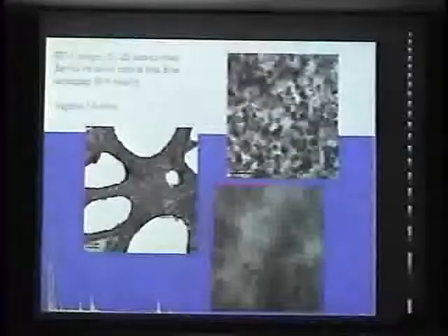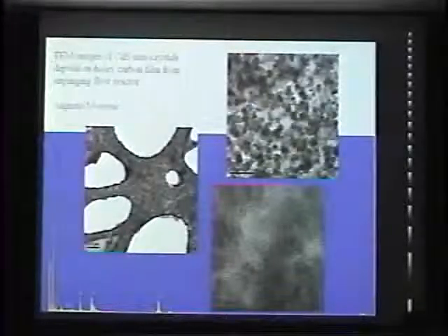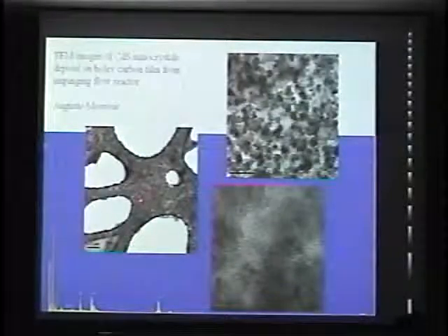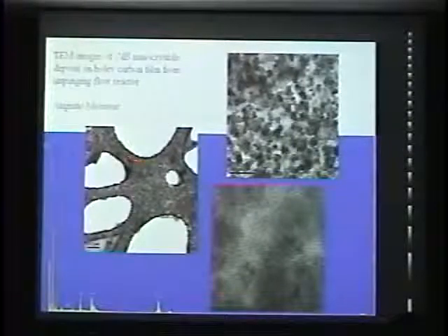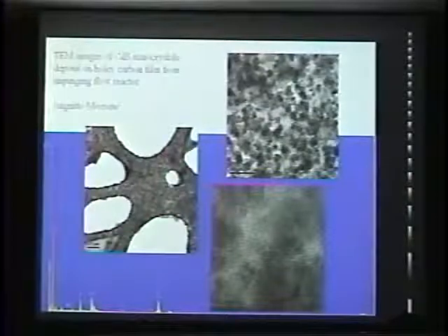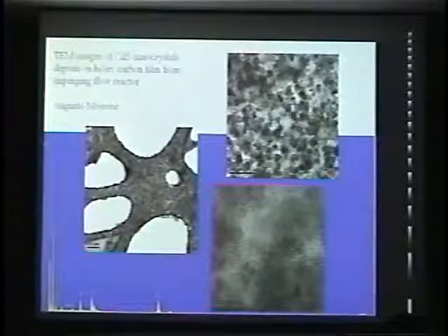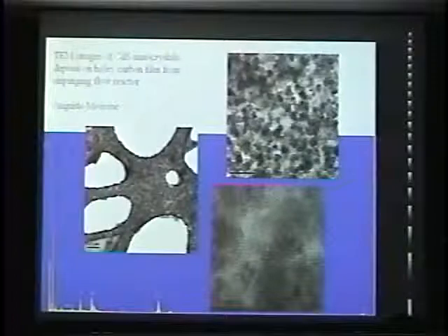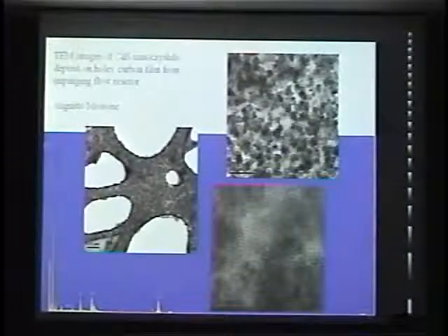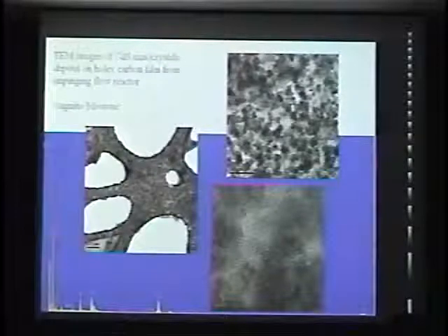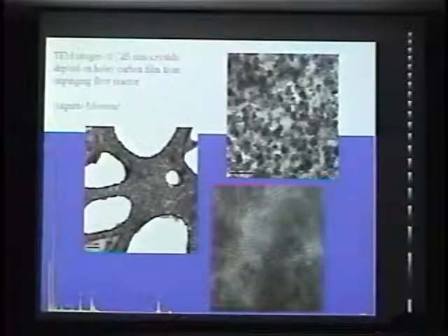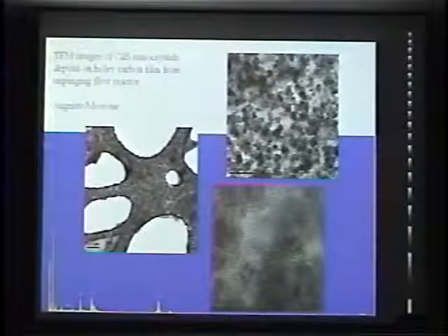But if you keep it there for a longer time, you can see this. This is a lacy carbon grid, and these are nanocrystalline cadmium sulfide deposited on the lacy carbon. They are not as highly oriented as the ones on the silicon coupon, because I think they don't like to grow on the lacy carbon film. But it shows the particles form more through molecular level growth, instead of particle sticking, because in the flux, there's no particle forming.